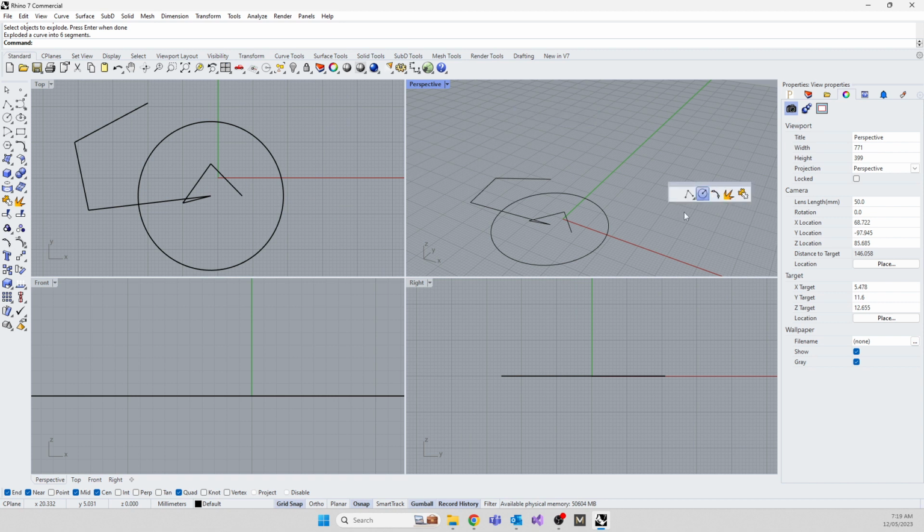So this is a quick way to group stuff under the middle mouse button for you to use. You keep all your tools, and don't have to keep looking for a tool you use a lot. After you've popped it, same as any other toolbar, grab it on its edge, now it's out, and you can bring another tool in there. So here's array, copy, etc. I call this housekeeping. It makes drawing faster and more pleasant because you're not running around the interface trying to find stuff the whole time. If you close that, it doesn't matter because now it lives under your middle mouse button.